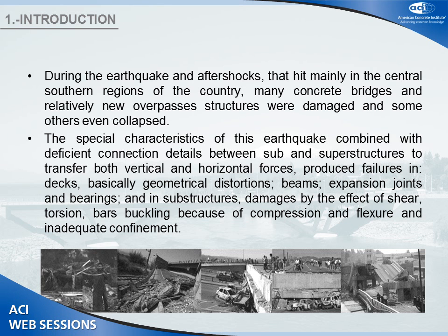During this big earthquake, there were a lot of failures in bridges, mainly because of some design details, like deficient connections between sub and superstructures, and that produces mainly geometrical distortions in plan of the decks. And also other problems like failures because of bar buckling, because of inadequate confinement.